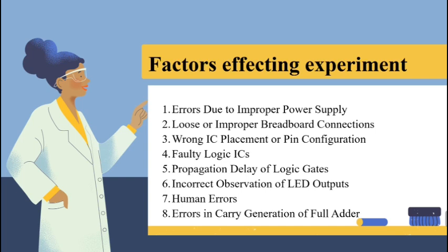To prevent this, carefully label carry input and carry output. Verify all the 8 possible input combinations. Cross check the truth table.